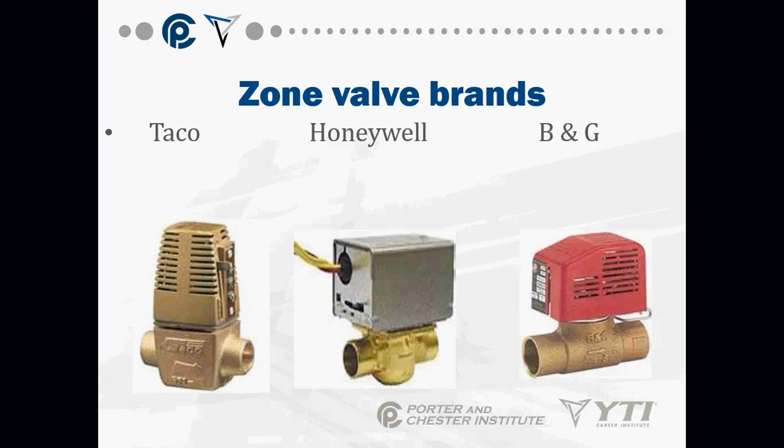B&G, they do cost a little bit more money, so people tend to steer away from those, especially in residential. Taco ones, they're nice. Taco and Honeywell are actually serviceable in the field. This top portion can come off and you can replace it, because this portion right here is typically what's going to fail on them. This is actually a heat motor, believe it or not, and this heat motor will open and close that valve.